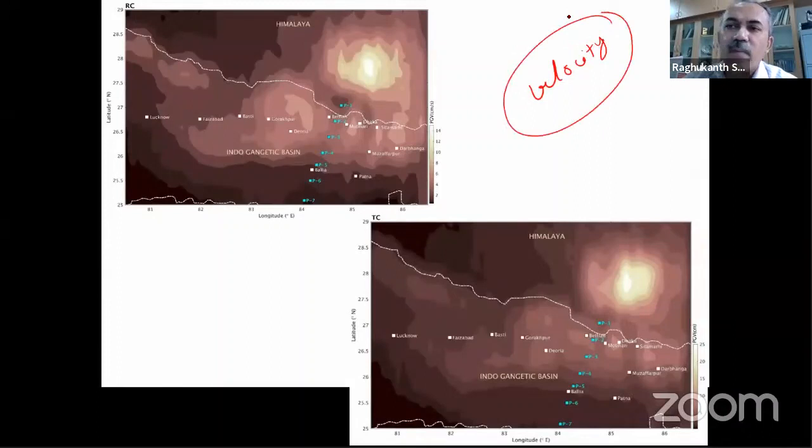So for the Nepal main shock, once the computational model has been calibrated, you can obviously simulate wherever place you like. For the Nepal main shock, we simulated these time histories, and then the peak values have been obtained. You can see this main shock is located somewhere here. In this region, because Himalaya topography is also there, the values are not axisymmetric.